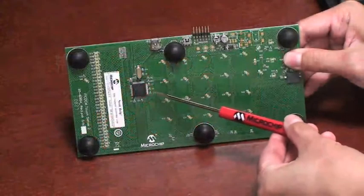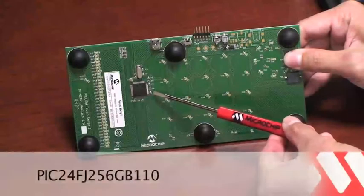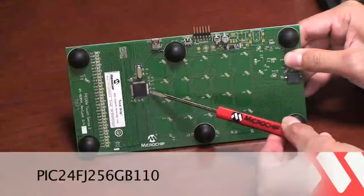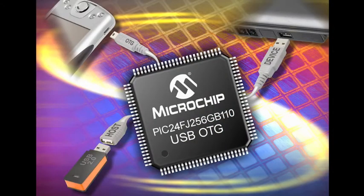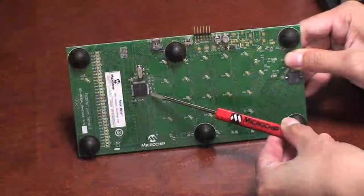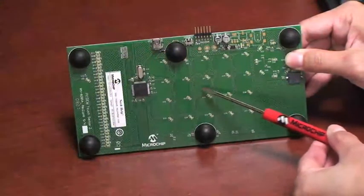At the back of the TouchSense tool board, you can see that it is controlled by the PIC24FJ256GB110 microcontroller. This 16-bit MCU has the USB on-the-go, 16-channel CTMU, and other peripherals. As you can see here, the CTMU drives the capacitive touchpads directly.